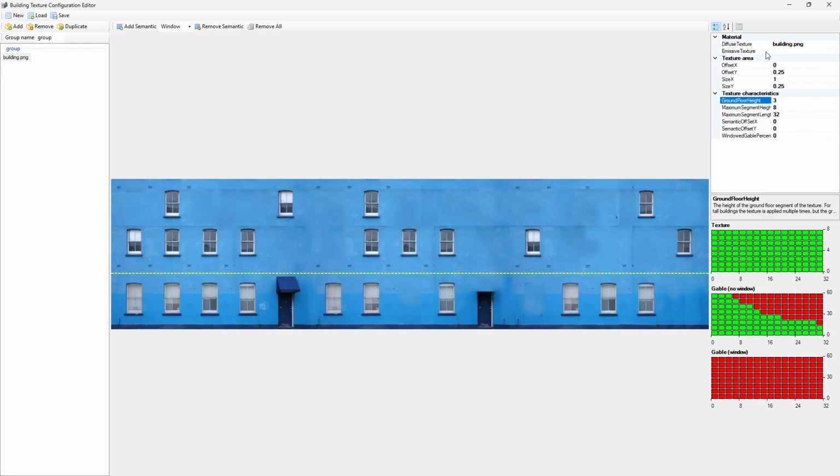Or if you have a night texture with your texture as well, you can add the name here. So you can specify like the building underscore LM texture or whatever. Do not worry too much about the extensions because the building algorithm will modify it to DDS textures automatically when it goes into ModelConverterX. And then you can use the material editor to convert whatever your sim needs.